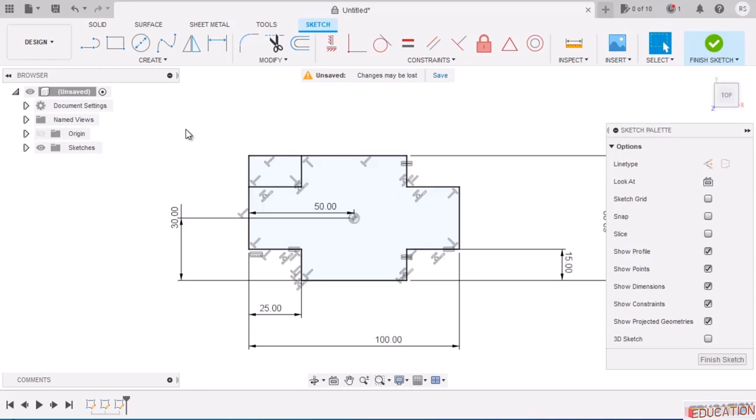How is it getting constrained? That we have to see. When I have drawn, you could see that I am taking this endpoint and moving in a horizontal way. So, this endpoint is already constrained, which is attached to this figure. So I am taking its reference and moving horizontal. And here, when I track this point and create that line, this line's length is getting fixed, which is equal to this line. So this entire thing is getting constrained. You will know about this after a few videos.